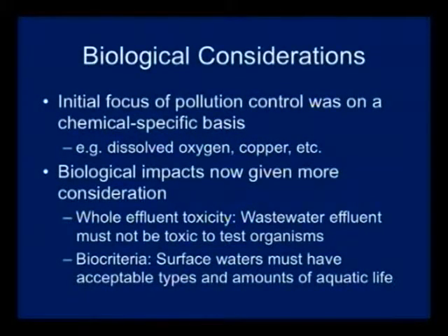If you operate a treatment plant now and you want a discharge permit, not only do you have to ensure that your copper concentrations are in compliance with standards and ammonia concentrations, you have to consider the cumulative effect, take a sample of your effluent, expose that to various organisms, and make sure that the combination of all of the parameters in your effluent are not causing toxicity. So there was a shift to biological conditions, not just looking at individual pollutants, but making sure the effluent as a whole was not toxic.